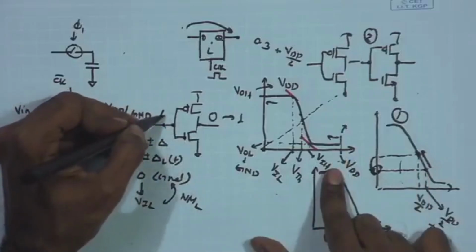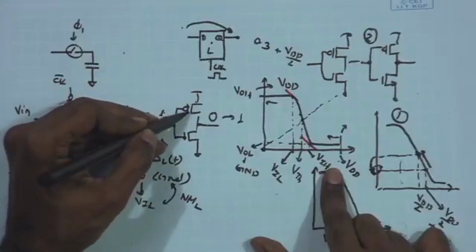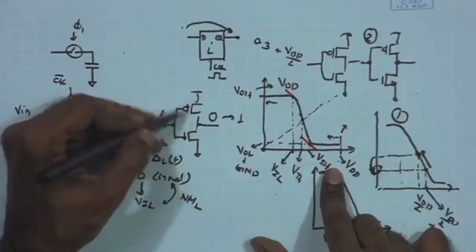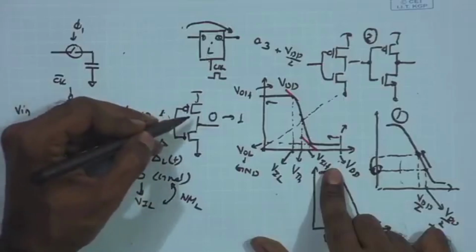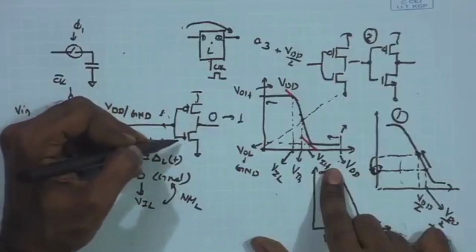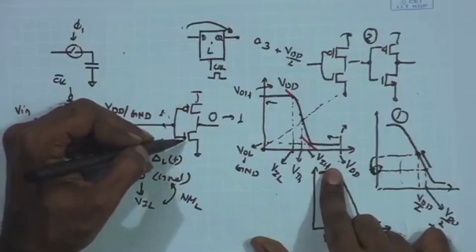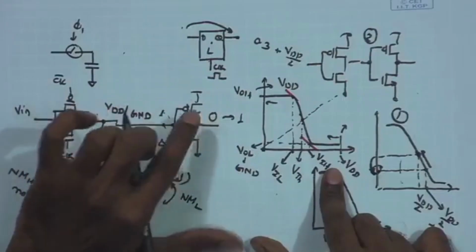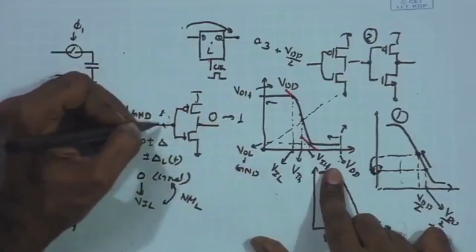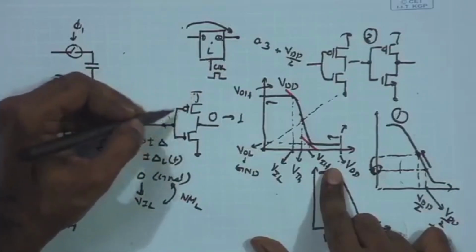But if the voltage over here starts dropping and we approach say VDD minus mod VTP, then this PMOS will start to get on, and if it goes further low, then it will be turning on more strongly, and the NMOS will be turning off relatively strongly. As a result, you can end up inverting the state. So, crudely we can say also from another perspective that the minimum degradation that you can obtain over here is going to be VDD minus mod VTP.